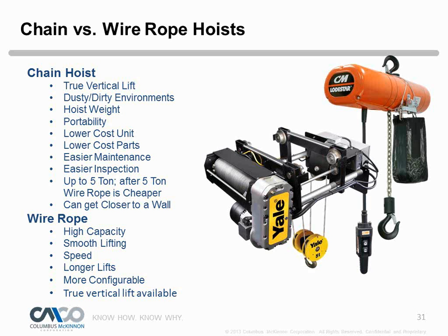So why a chain hoist versus a wire rope hoist? We talk about electric and air and things of that nature and the anatomy of each, but when do I go from electric? Sometimes it's more features and benefits because we do have the same capacities in both. But when we start to get really above 5 tons, we tend to start getting into the wire rope line, or where we need faster lifts.